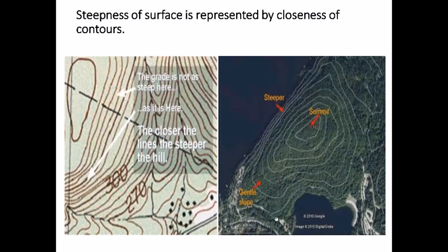So if you see this contour map for this area, if you don't have these lines, that's just a picture taken from the satellite, and it doesn't tell you much about how the elevations are changing, because it is taken from the top, and from the top it's difficult for you to judge the elevation of the land. So that is why on the same picture taken by the satellite, we introduce these contour lines or contour marks that can give a 3D picture of the same area.